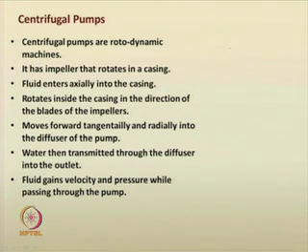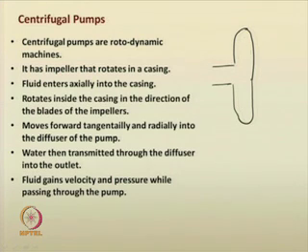Usually the fluid gains velocity and pressure while passing through the pump. I can just give a brief sectional view of the centrifugal pump. As we mentioned, it is a type of rotodynamic machine. So, you can have the sectional view, say a casing is given here, connected with an inlet, and it consists of impeller blades.